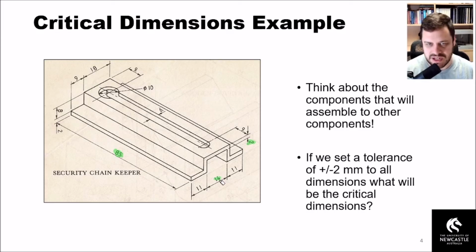Because we've deemed the 14 to be quite important, the 18 would inherently be important there as well, because naturally if our 14 was, assuming it wasn't a critical dimension, 16 millimeters, and then we did deem that 18 to be a critical dimension, you've only got 1 millimeter of thickness left in here, so that's why we would deem that one to be important.